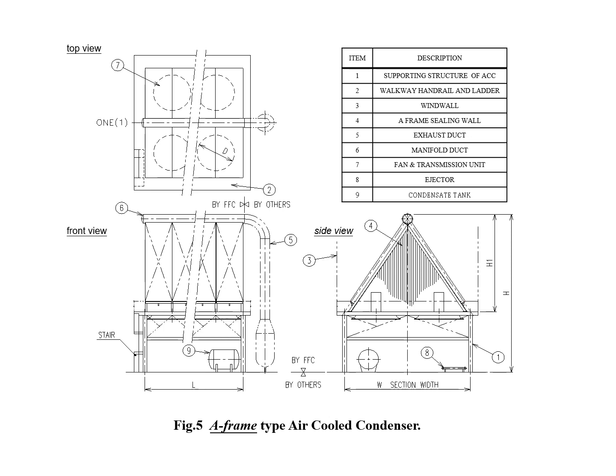People may ask, why are the bundles placed at an angle to the horizon? The reason is to reduce the occupied area of the heat exchanger. To enhance its effectiveness, the heat transfer area is designed as large as possible. We arrange the heat bundles at an inclined angle to the horizon in order to keep the occupied area of the heat exchanger small.